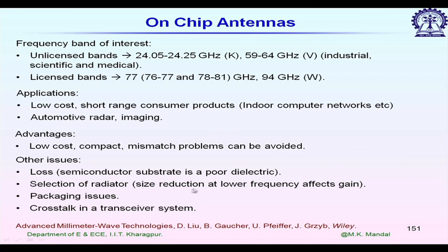And size of antenna, it actually influences the radiation characteristics. Gain of the antenna decreases with the effective area, the physical dimension of the antenna, and loss increases with the reduced size of the antenna. Bandwidth also decreases with reduced size of the antenna, and antenna efficiency again decreases with the reduced size. So, for all the on chip antennas, we will be facing these problems.